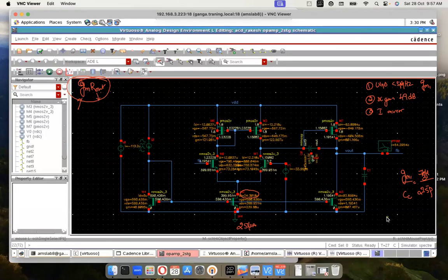Ideally, if you have the absolute value of VTH for a given W and L, probably you will be able to fix everything in one go. But I wanted to show you iteratively what the points are that we can consider to finally reach where we would like to be. Right. So any question till here? I know we fixed the current mirror, that's fixed.